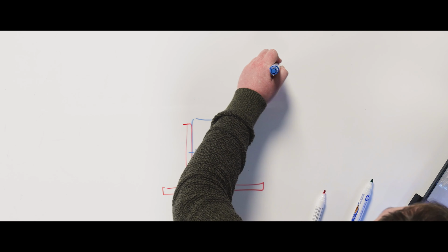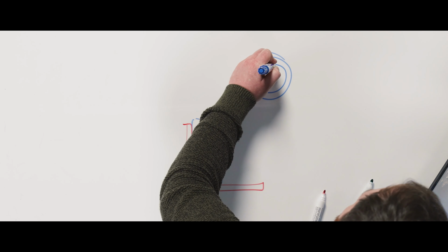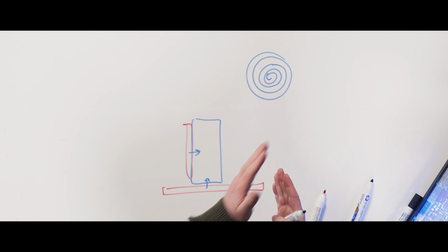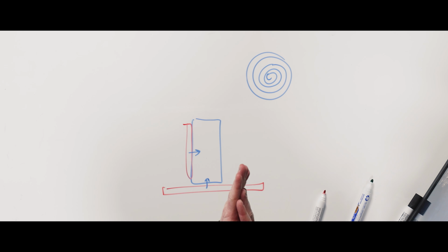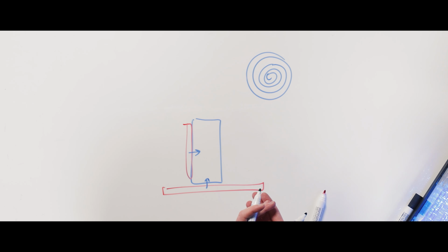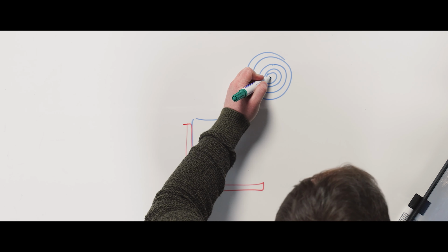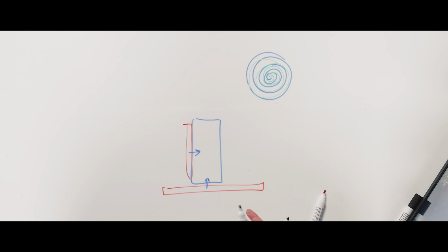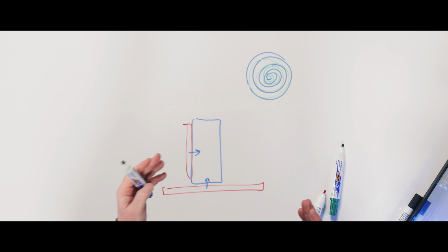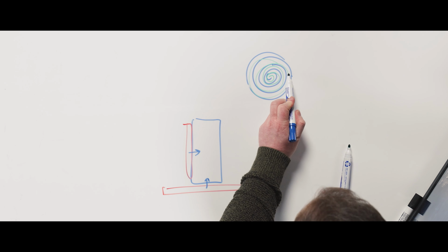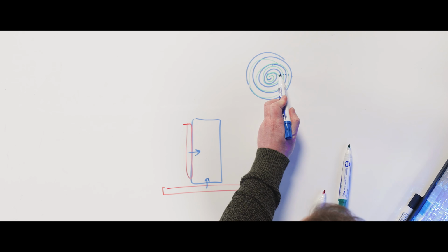And the reason for that is inside of the battery cell, it's basically a spiral wind of anode, cathode, and separator. So basically plus, minus, and something to stop plus and minus from touching. That separator, remember what we spoke about earlier, an insulator, is not electrically conductive, which means it's not thermally conductive. So that exists in between each of these layers. So while the anode and cathode and electrodes are very conductive, it's basically going from very conductive, not conductive, very conductive, not conductive, very conductive, not conductive.